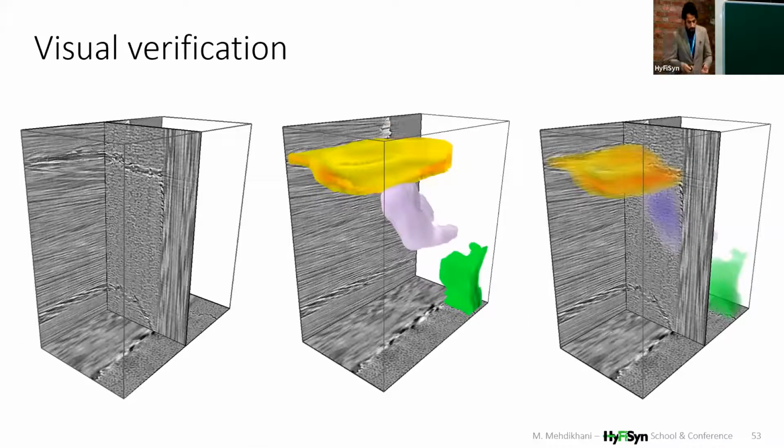And again, we have somehow the loss of damage detection by DVC due to too large damage features. We can visually check if the features that are detected here correspond to real features. And as we can see, this transverse crack is present there. So DVC has detected correctly that transverse crack, and also the fiber splitting, which is shown here, is well detected. To look at the delamination, maybe you can see something here as sort of delamination. So the three features that we have detected via global DVC actually correspond to real features and are correctly detected.